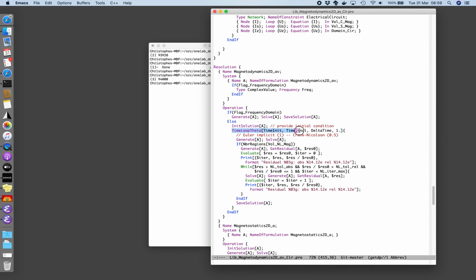And then we apply a time discretization scheme. What we do here is what is called the theta time scheme, and you know about this scheme because you learned about it. Over here, I specify the theta parameter to be 1, which leads to an implicit Euler time integration, the simplest time integration scheme, which is unconditionally stable. So you can take extremely large time steps. Of course, if you want accuracy, you need to refine time, but you have no constraint on stability.